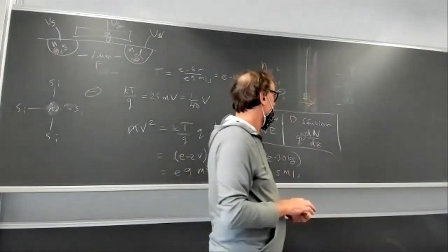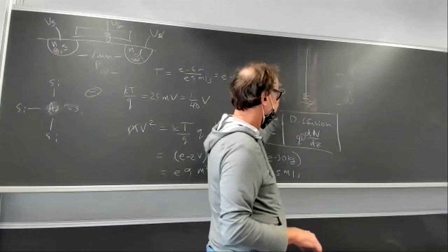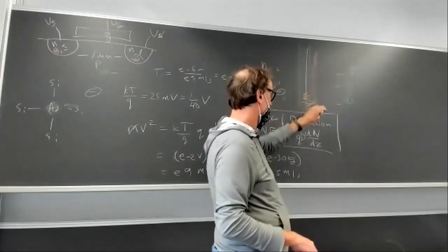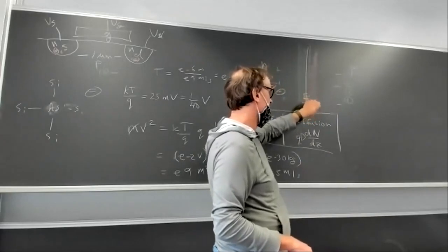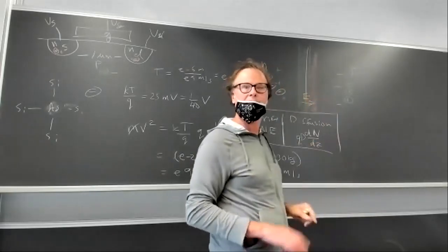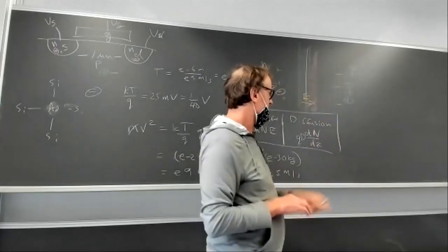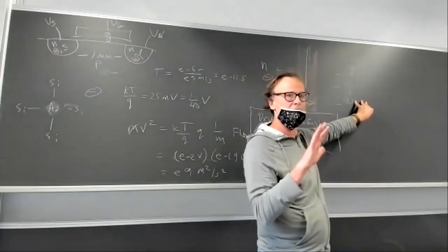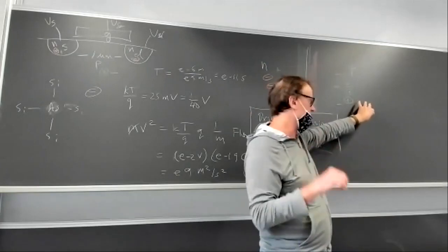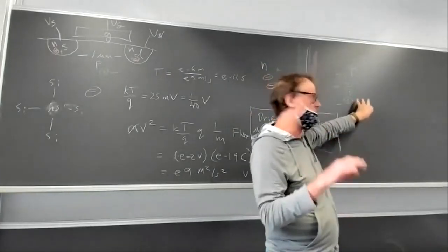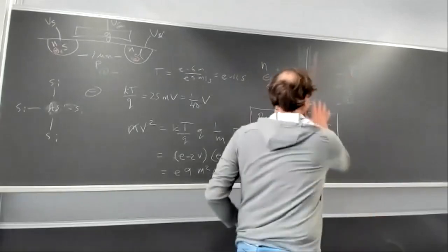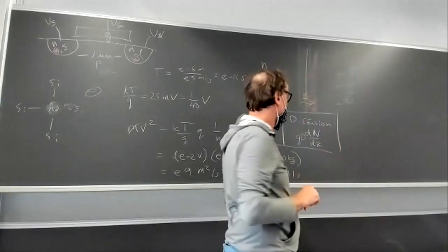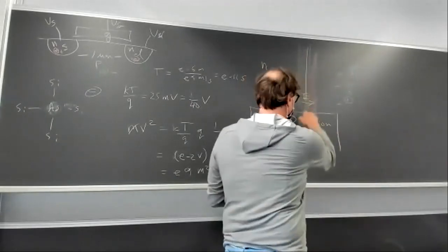There's a big diffusion current for both electrons and holes, but it's balanced by the electric field acting on the concentration gradient everywhere. Out here, there's no concentration gradient. It's all neutrally charged. There's no drift current and no diffusion current. Everything's just uniform.